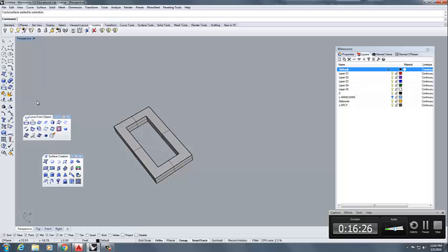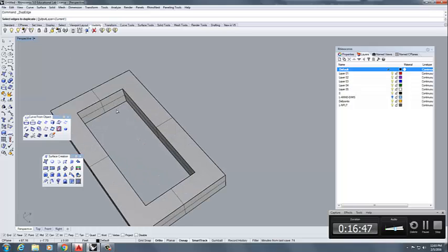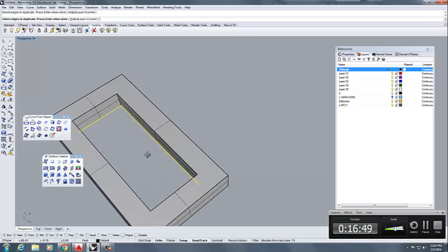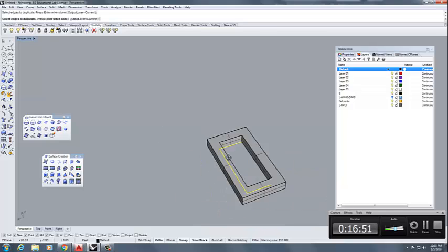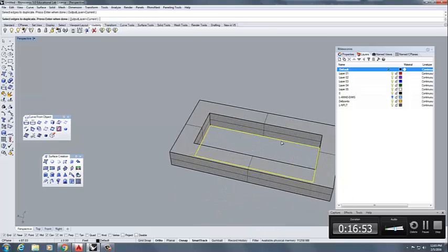is this menu right here. Project curves is the command that is most often used, but it's in the curve from object. You could type curve from object, but if you hover over it, you can see the third command is duplicate edge or duplicate border. I'm just going to use duplicate edge. It says select edges to duplicate. I go in, I click that one, I'm going to orbit around, that one. I don't have to hold shift because the command's still set. It says, okay, press enter when you're done. I'm good. I can hit spacebar or enter.